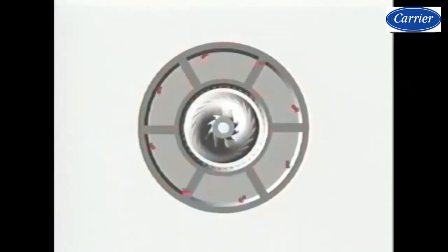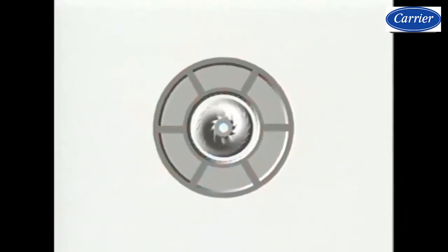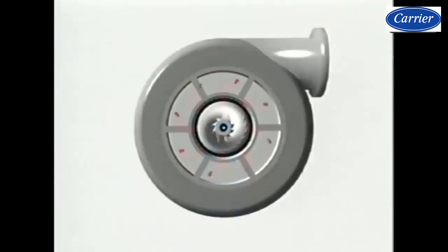In the animation we can see how the compressor works. The regulation of the flow of this type of compressors when they do not work at 100% is by varying the amount of refrigerant that will enter through the center of the impeller. In this way we can regulate that more or less refrigerant enters depending on the thermal load